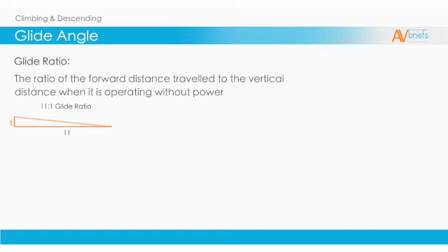You can replace the term units with feet, or meters, or millimeters. It doesn't matter what you replace it with. It just means the same thing. On the far side of the ratio, a glider, which is made for gliding, will have around a ratio of 20:1. That means for every 1 unit of lost height, it will travel forward 20 units. That's nearly twice as efficient as our training airplane. So the glide ratio is an important figure, as it tells us how far we will travel if we lose engine power.